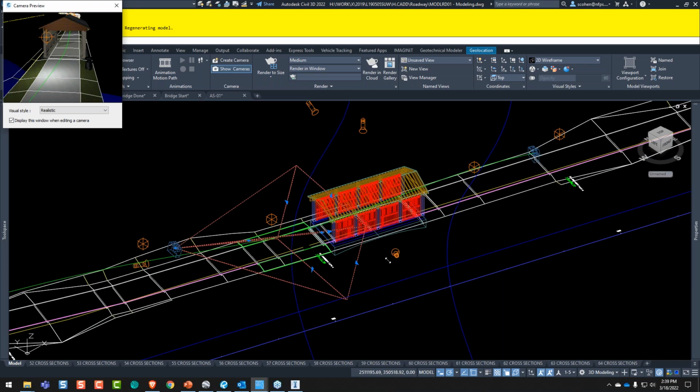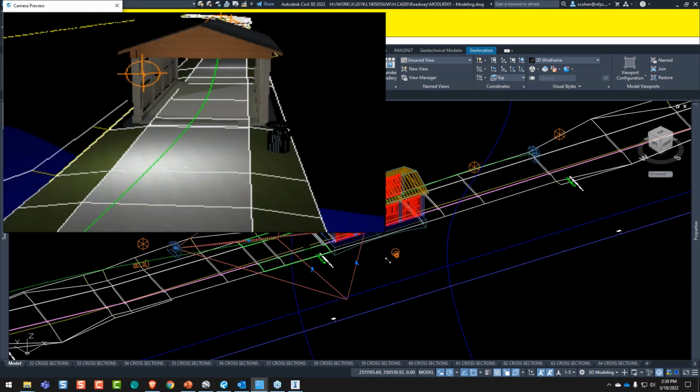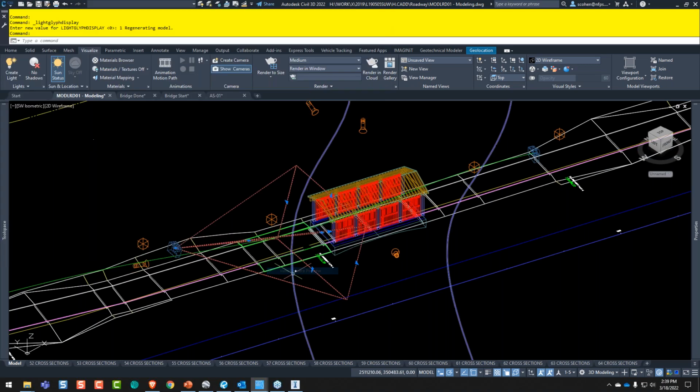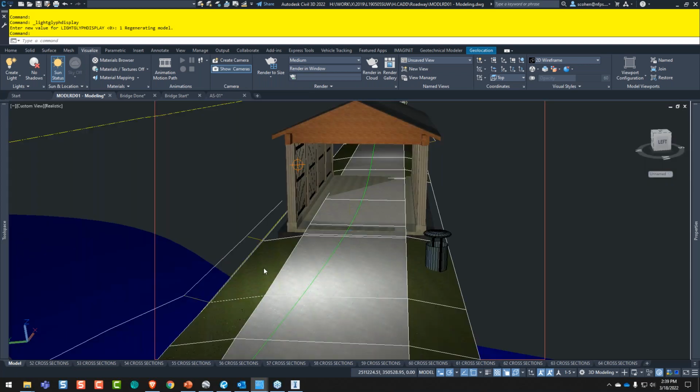I'll try and make this a little bigger without it crashing. But as you can see, with those spotlights, I put them in different spots, so it would do a nice job. Now you're seeing the lines kind of work. Actually, while I have this selected, let me set my camera view. Let me do it again. Set camera view. That sets the view to the camera, which is kind of cool. It actually puts it right in the AutoCAD drawing, realistic and everything. Now I'm seeing the corridor model, so I don't want to see that.